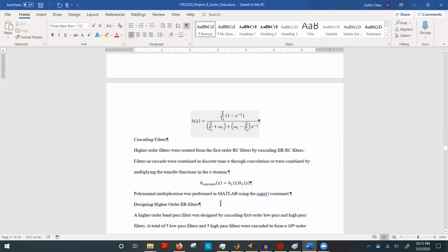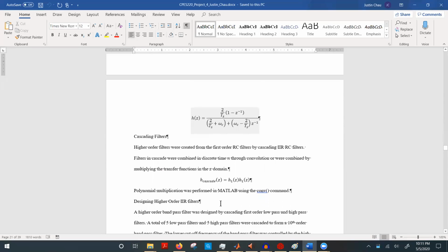That's a lot of multiplication, and you can write it out, but instead of trying to write out all the multiplication, I think you could use Pascal's triangle to help generate some of those coefficients. But instead of doing that, we can just use the MATLAB convolution command. It can be used for vector or polynomial multiplication by inputting the coefficient vectors for the polynomial.